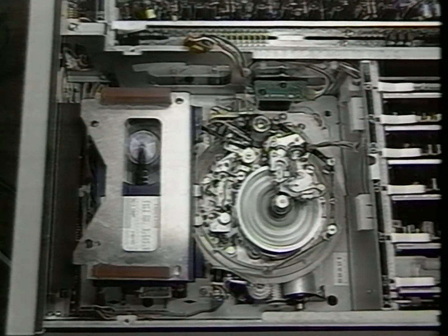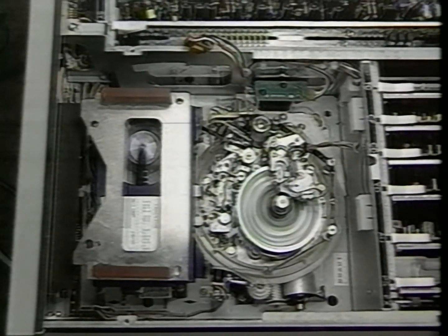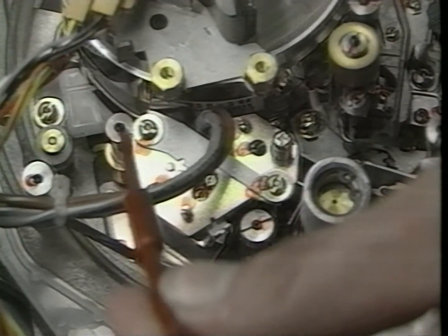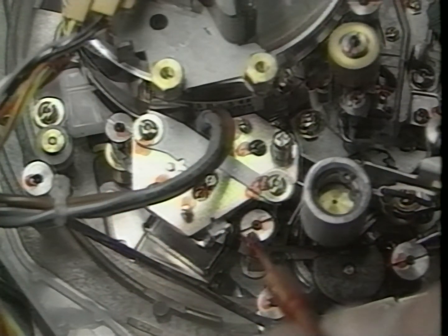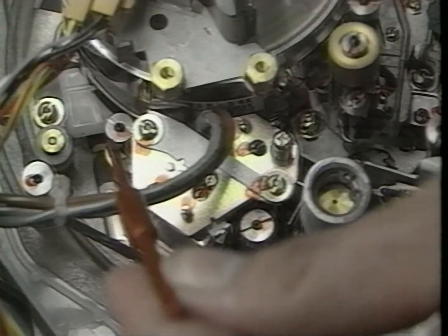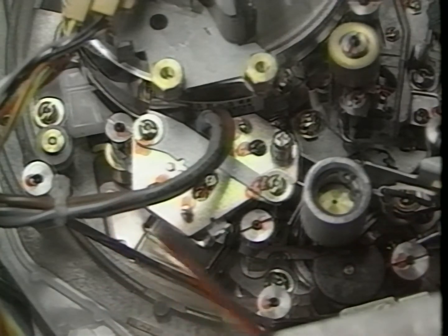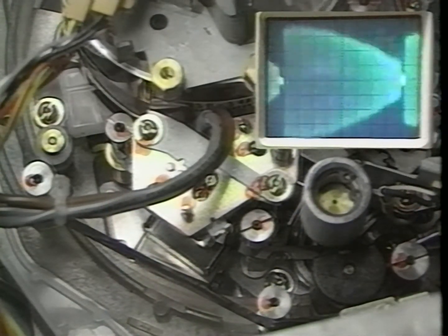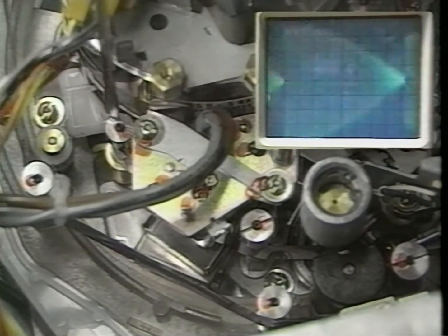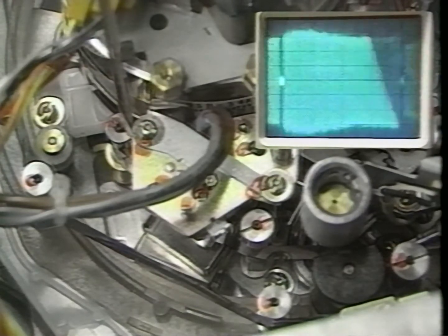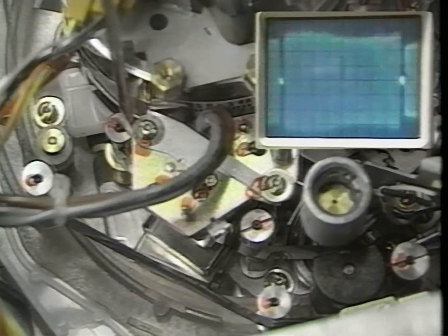In step 3, the linearity of the exit side is adjusted. This procedure is very similar to that used for the entrance side. Tape guide 3 controls the upper edge and tape guide 4 controls the lower. Tape guide 3 should have a clearance at the upper flange and tape guide 4 should be adjusted so that there is a slight nonlinearity on the exit side. Tape guide 3 is then adjusted to correct this nonlinearity and make the envelope flat.